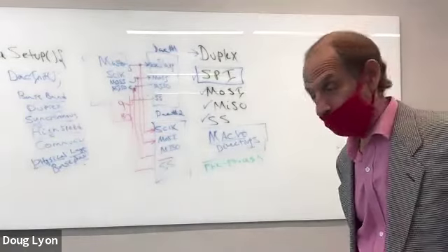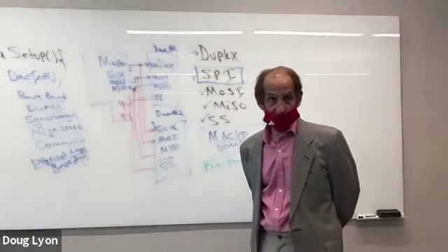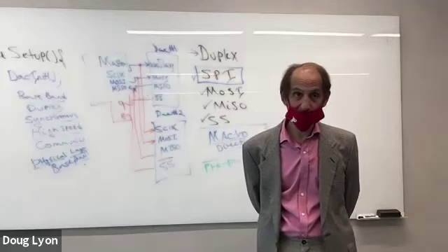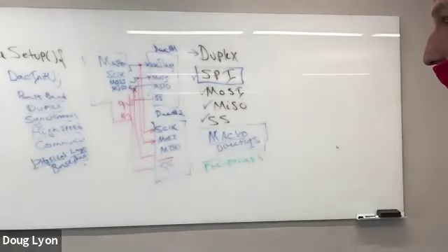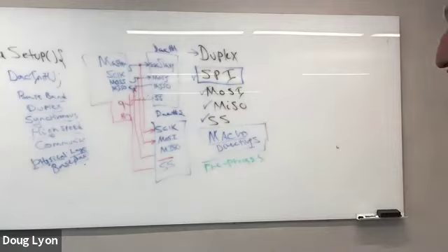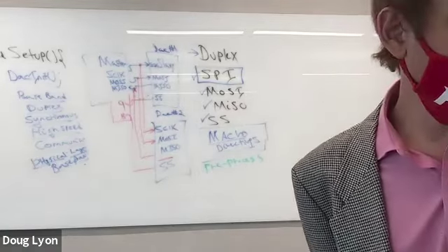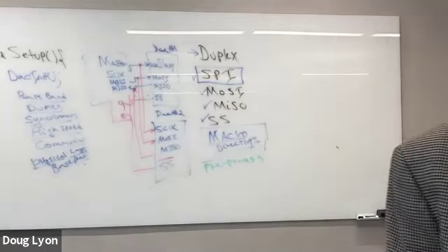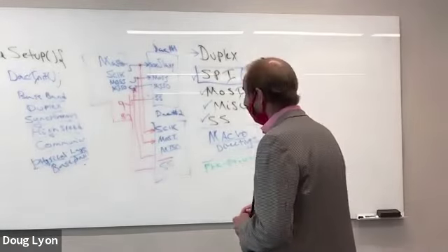So in comparison to the servo, which used a baseband modulation technique called pulse width modulation for adjusting its angle, here we're actually using digital data communications, using a baseband duplex synchronous high-speed communication physical layer in order to be able to do our communications to the various chips that we're going to add to our little Arduino. And that is an example of our first bus, right?